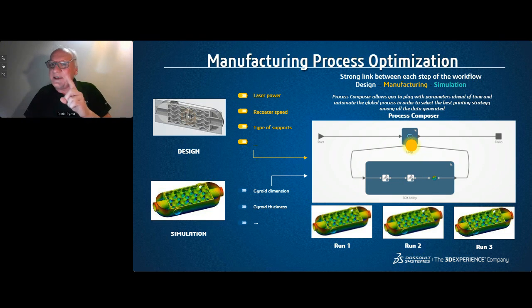If for any reason you cannot manage to reduce the distortion enough, there is a magic tool in CATIA called virtual to real shape morphing. Virtual to real shape morphing can take the simulation, the prediction of the distortion, and compensate the geometry. So it goes in the opposite direction. You will deform the part to get a wrong part, but a final product perfect regarding the specification.